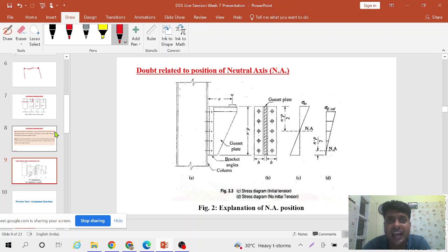In the design of the gusset plate, if several members are coming on a section, then in the long type of question you will be asked for each member. So for each member we will check. If at every position your connection is fine, then your gusset plate is fine, so no need to calculate for the final resultant.